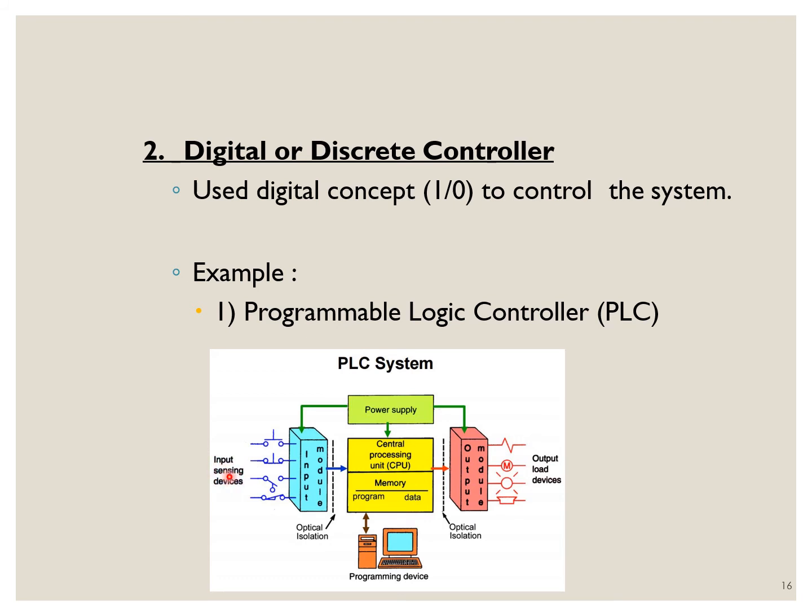The sensor signal will be sent to the input of this PLC system, and then the input will be sent to the CPU, which is programmed inside the device, and we can make changes or monitor from the device. This CPU will act as our controller, make a decision and send the output signal to our final element device.